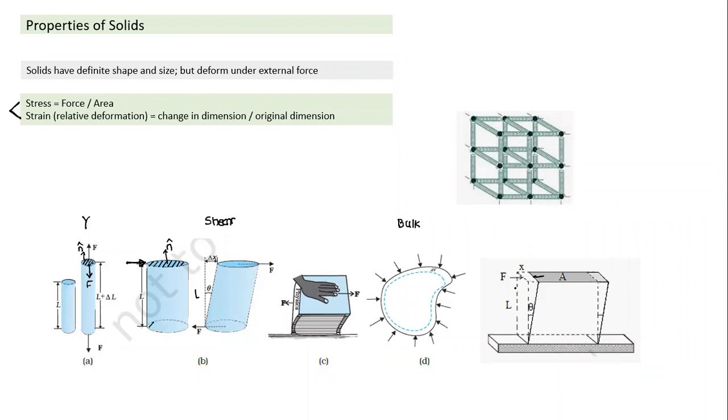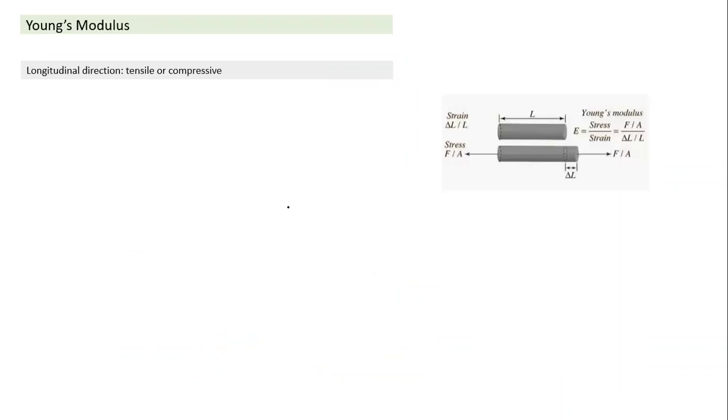So this is what we, three things we need to understand, three kinds of modulus. Longitudinal stress by longitudinal strain, shear stress by shear strain, volumetric stress, which is pressure, by volumetric strain. And for each of these three ratios, the dimensions are the same. All ratios, the unit is Newton per meter square. Strain is dimensionless. Only the nature varies. The stress-strain ratio is a property of the material. That's a unit.